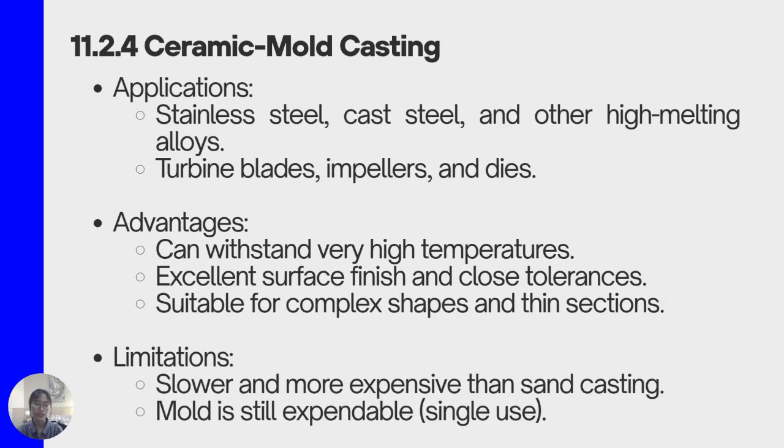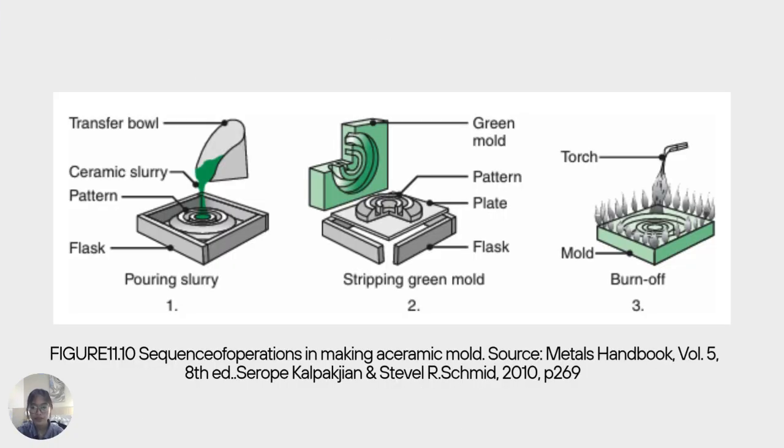Common applications include turbine blades, valves, and precision engineering components. Although the molds are expendable and more expensive than sand or plaster molds, they offer superior performance and quality for high temperature alloys and critical parts. This is a sequence of operations in making a ceramic mold.